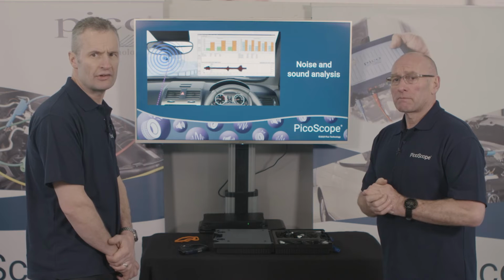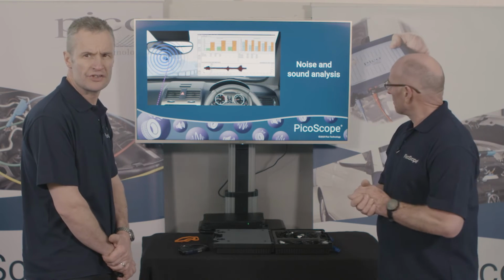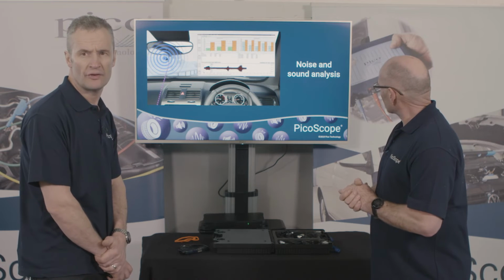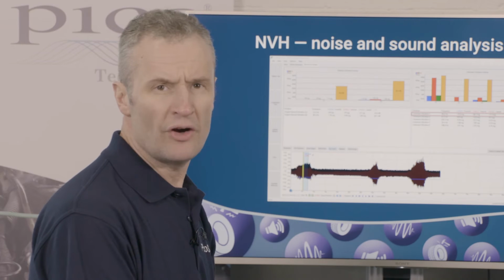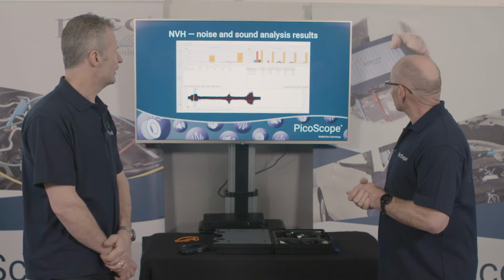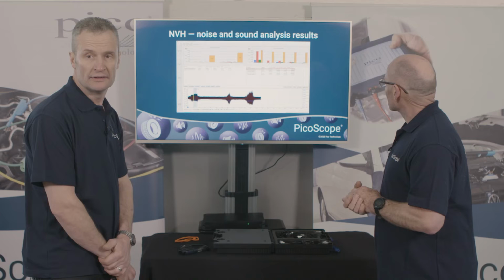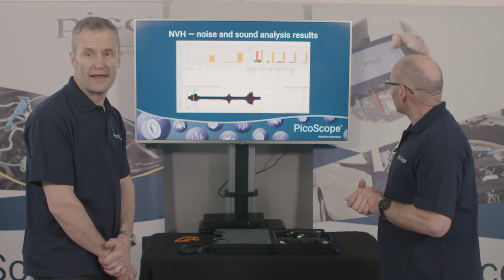Yeah, that's exactly right, Frank. And the view we've chosen there, on the right-hand side, the bar graph view, is showing the top 5 unknown vibrations. We've highlighted vibration 1, 39 hertz it is, peak vibration detected by the accelerometer in the vertical axis, but also detected by the microphone inside the cabin. So I think we're certainly tuned into the customer's complaint. Let's go and replicate this on our van.